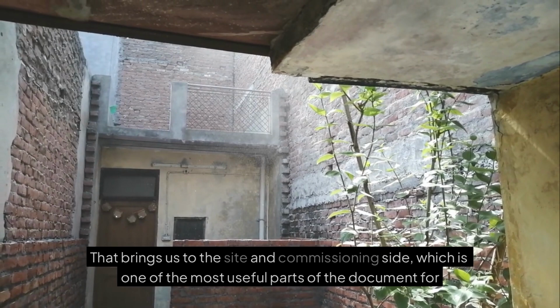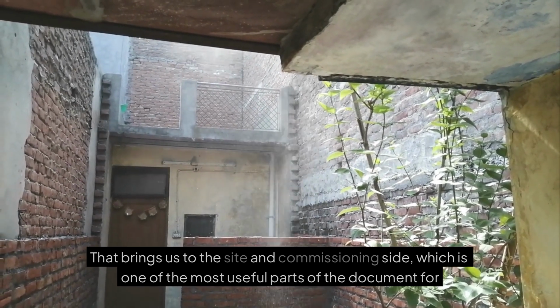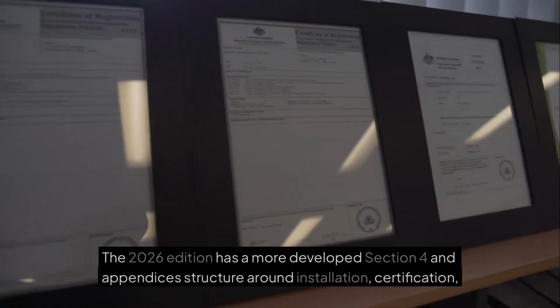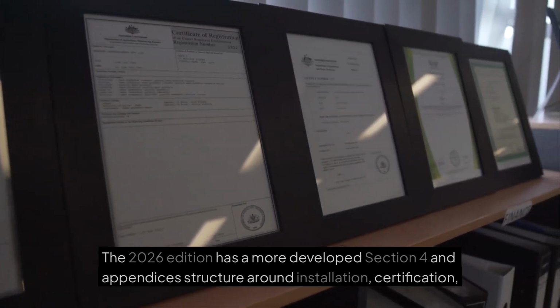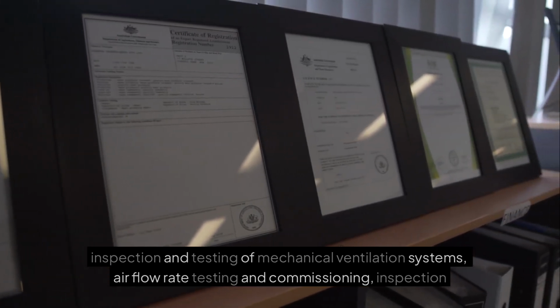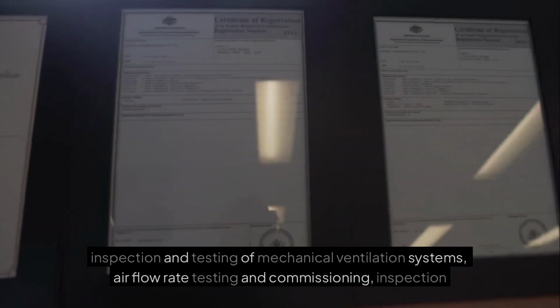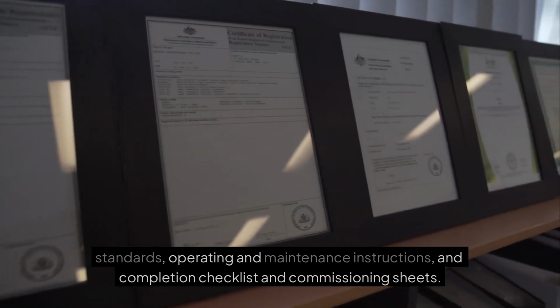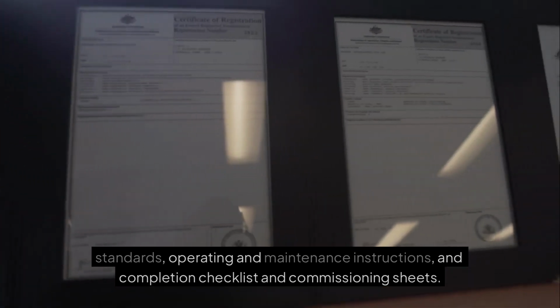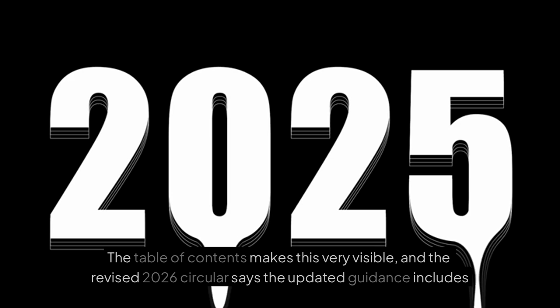That brings us to the site and commissioning side, which is one of the most useful parts of the document for someone starting out. The 2026 edition has a more developed Section 4 and appendices structure around installation, certification, inspection and testing of mechanical ventilation systems, airflow rate testing and commissioning, inspection standards, operating and maintenance instructions, and completion checklist and commissioning sheets.